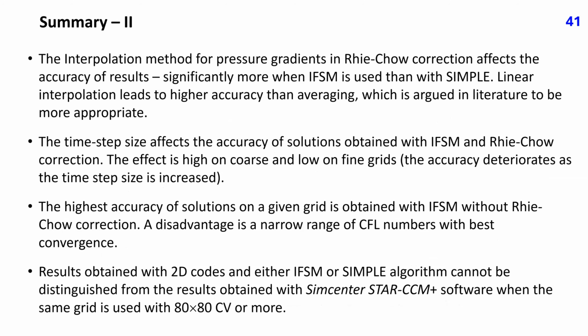The interpolation method for pressure gradients in Rhie-Chow correction affects the accuracy of results, significantly more when IFSM is used than with SIMPLE. Linear interpolation leads to higher accuracy than averaging, which is argued in literature to be more appropriate.